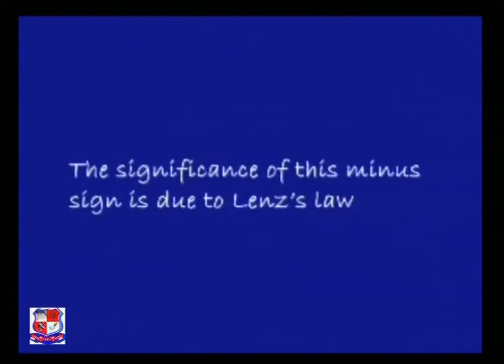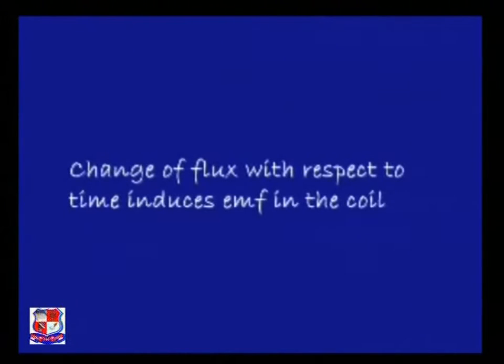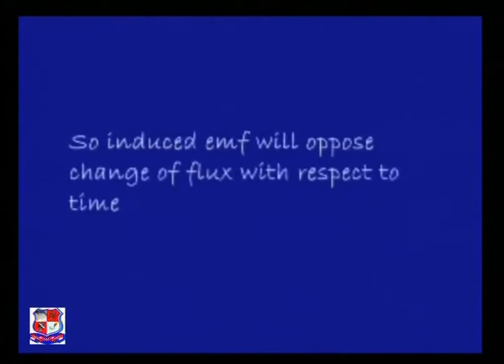The significance of this minus sign is due to Lenz's law, since the induced EMF opposes the very cause of it, that is the rate of change of flux with respect to time. It means change of flux with respect to time induces EMF in the coil. So induced EMF will oppose change of flux with respect to time. Hope you understand. Thank you.